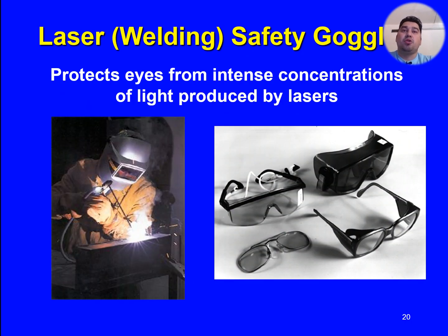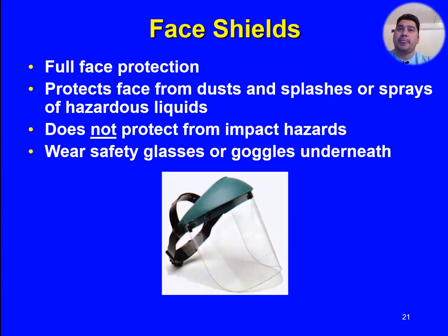Now, laser welding safety goggles protect eyes from intense concentrations of light produced by lasers. So whenever you are using goggles for laser, do not use the ordinary ones. There are specific goggles for laser work that you have to use. Now we have the face shield, full face protection from dust and splashes or sprays of hazardous liquids. This will not protect from impact hazards, only dust and any splashes or sprays.